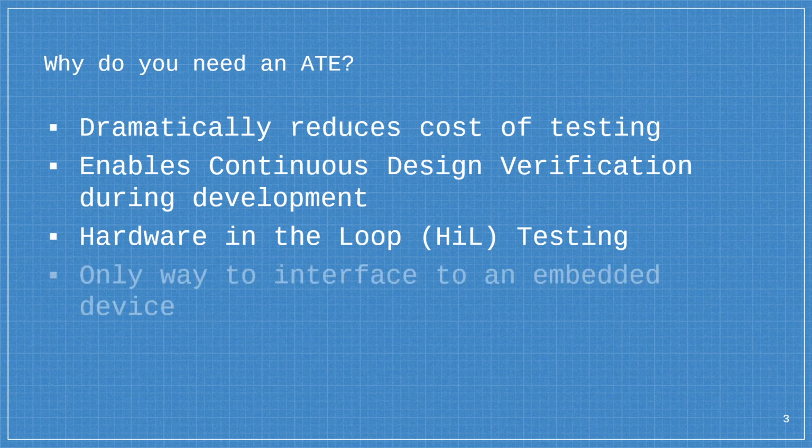And in a lot of cases, it's the only way to interface to an embedded device, especially a flight computer or a subcomponent of a larger system that has a high pin count. The only way to effectively test it is to hook it to some sort of automated equipment just to get to the different pins.